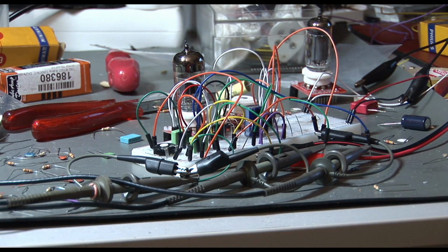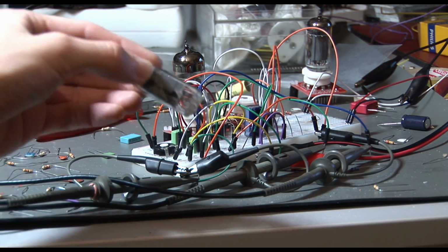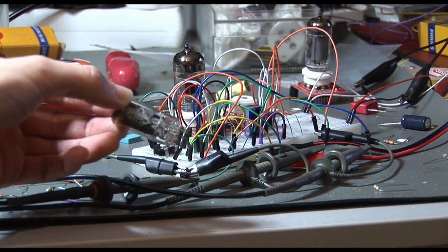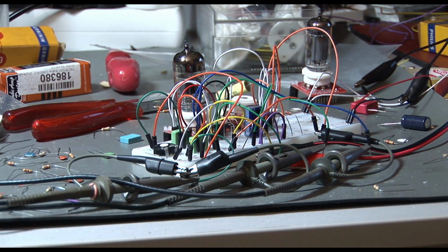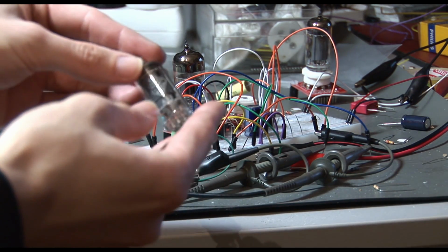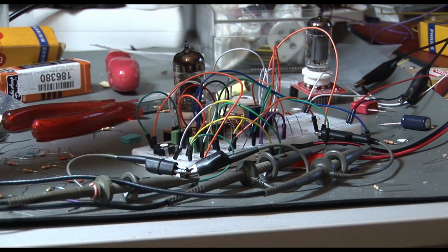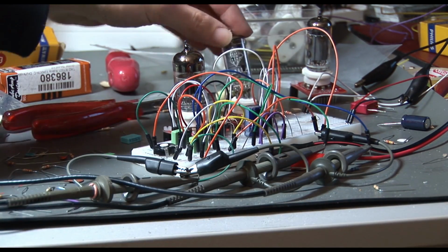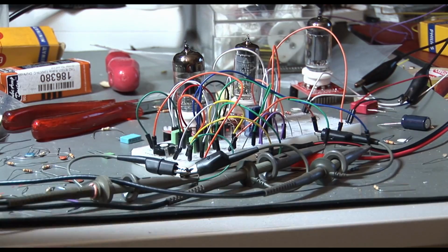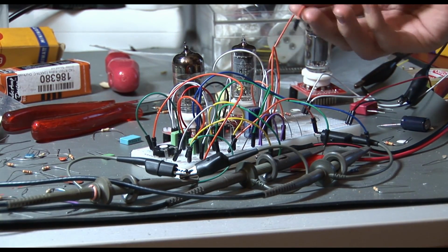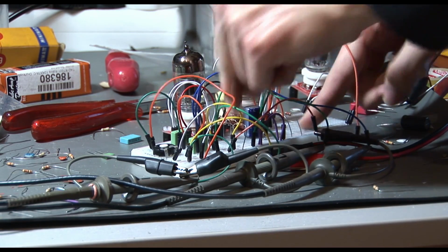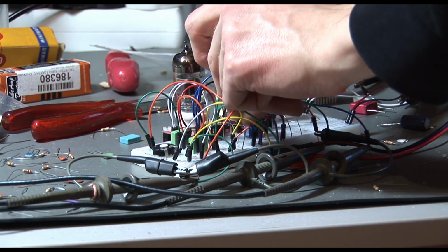Of course, as you have seen in the first video, I've already prepared everything. Here we have the pentode, which we will use, the 6AU6. It's also printed on here. Maybe you can read it, but you don't have to. Now I will plug it in. And now I have to change the circuit a bit so that the current source is actually in the circuit. So I will remove this common cathode resistor, put it aside, and connect the current source here.